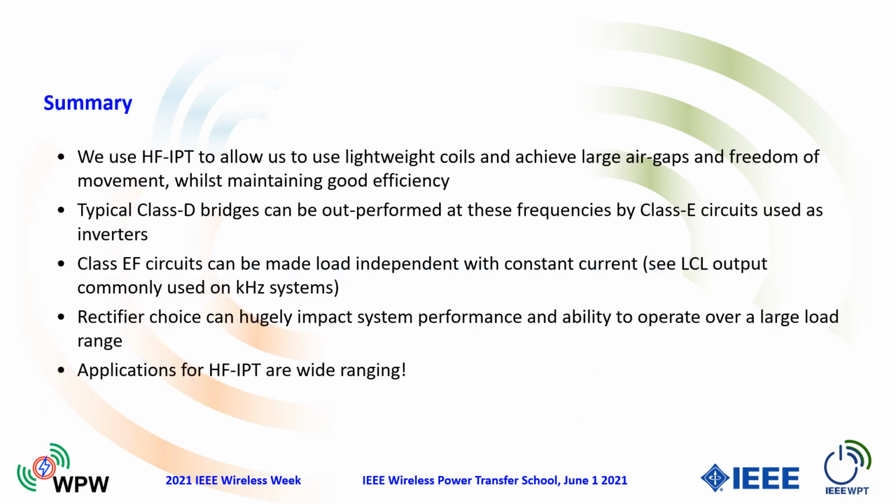So just to summarize then, we use high frequency IPT in order to be able to get lightweight coils and achieve large air gaps and freedom of movement. And also we can maintain good efficiency over these changes in operating envelope. We typically use Class E or Class EF types of inverters. They typically outperform the Class D type solutions, and if they're designed properly, they can achieve soft switching over a very wide load envelope.